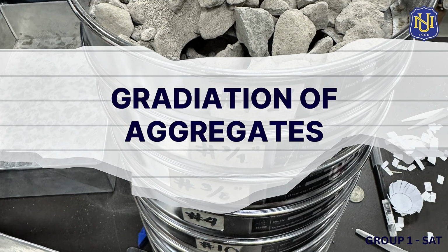Good day, everyone. In this experiment, we will discuss the gradation of aggregates through sieve analysis. This activity is one of the most important laboratory procedures in construction materials testing because aggregates greatly affect the strength, durability, and quality of concrete. Aggregates are classified into two main types: fine aggregates, which are commonly sand, and coarse aggregates, which are commonly gravel. These materials occupy a large portion of concrete volume, making their proper grading essential in construction projects.